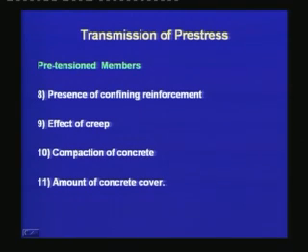As I said before, the compaction of concrete is very important regarding transmission. A well compacted concrete will have a lesser transmission length and the prestress transfer will be better. And also it depends on the amount of concrete cover around the prestressing tendons, because if we have more concrete, then the prestress transfer will be better.